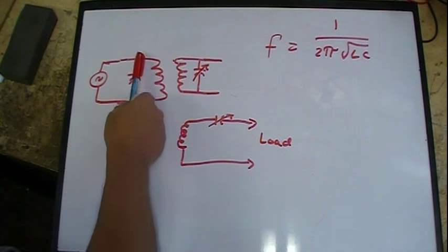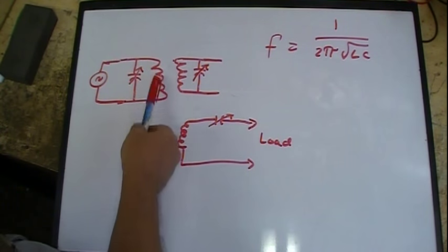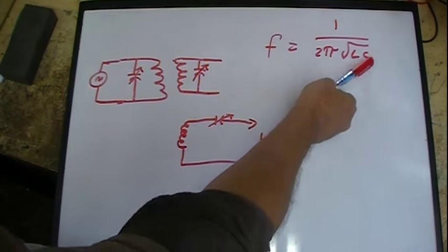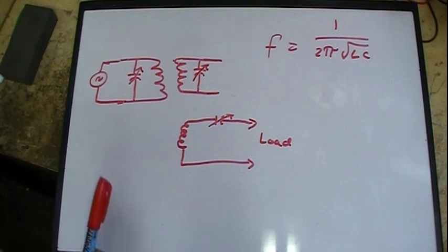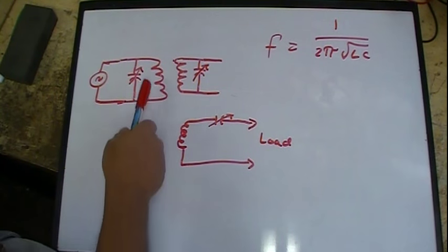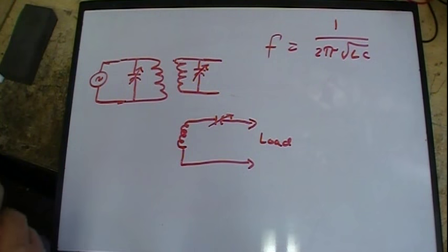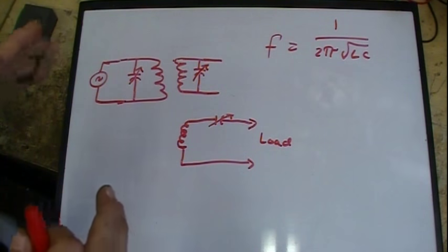So if you were actually going to design one, you could use the same size inductor and capacitor to make up that IF transformer. And you generally see that. Most IF transformers are 1-to-1 transformers. You don't really ever measure the true impedance.